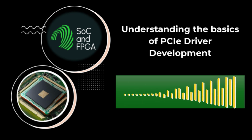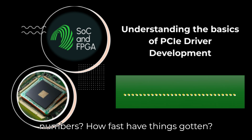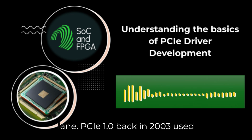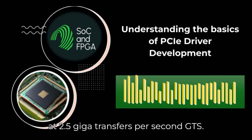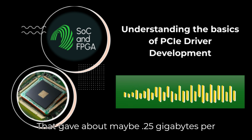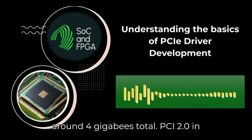That's definitely good news. Our sources had a table summarizing these speeds. Can you walk us through some key numbers? How fast have things gotten? Sure, let's look at the raw speed per lane. PCIe 1.0 back in 2003 used something called 8B10B encoding. It ran at 2.5 gigatransfers per second, GT/s. That gave about 0.25 gigabytes per second, GB/s per lane. For x16, that's around 4 GB/s total.